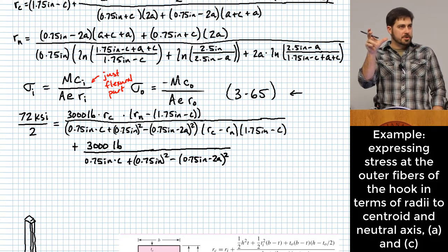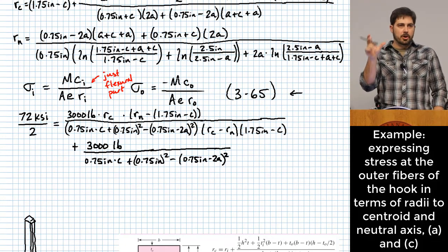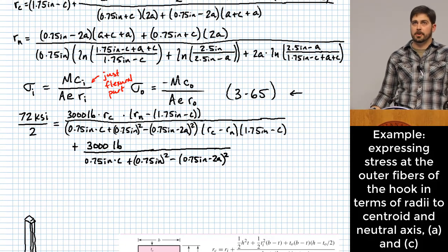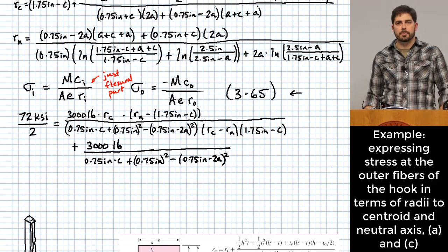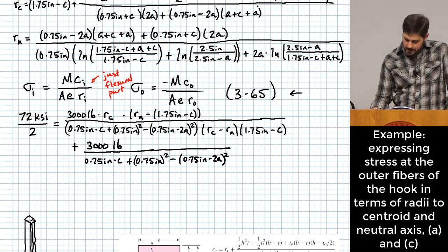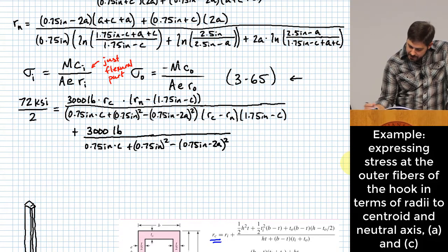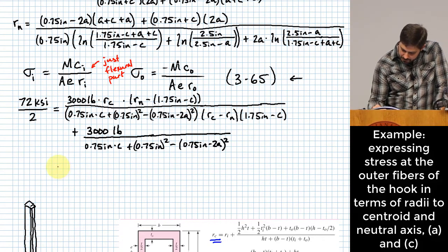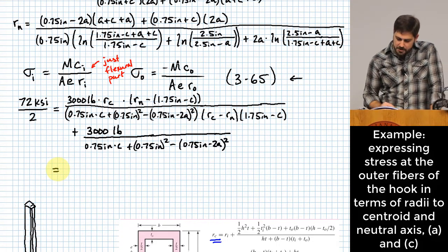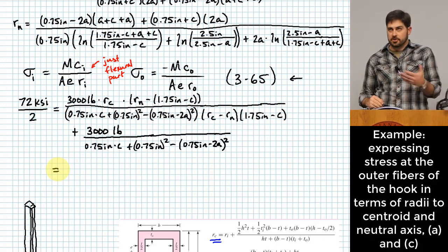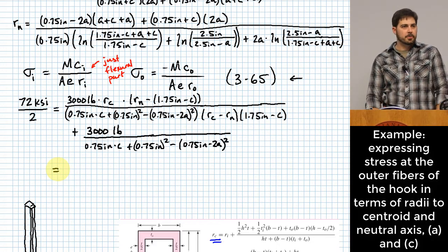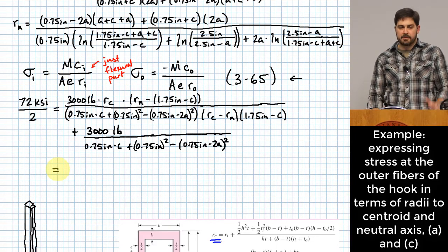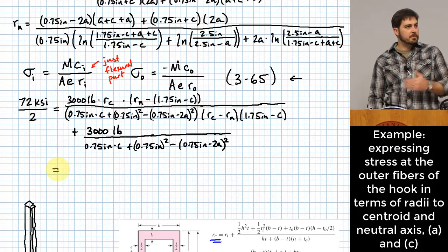Okay, imagine if the length basis wasn't very large, right? The moment arm wasn't very large. You could end up with a larger amount of stress due to your axial component than you do due to the flexural component. But anyway, let's presume here that it is in compression, in which case we want to take our strength value, and because this is a ductile steel, we presume that it is going to have the same strength properties in tension and compression.